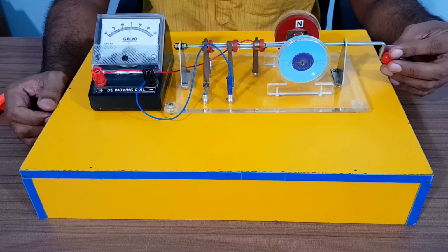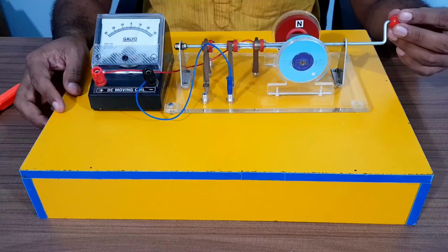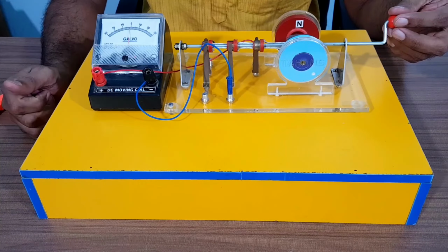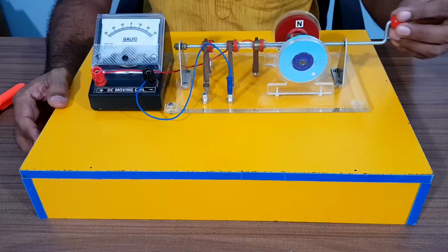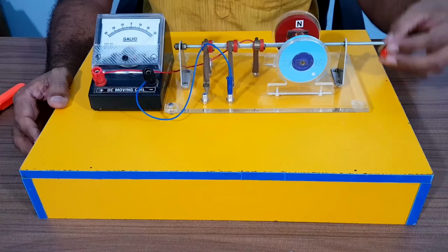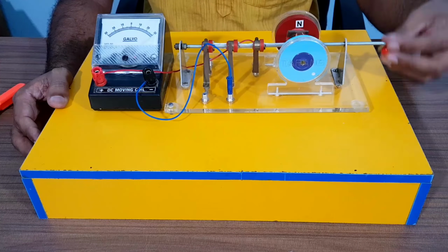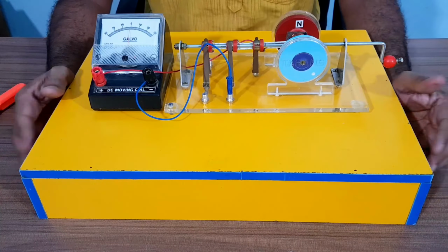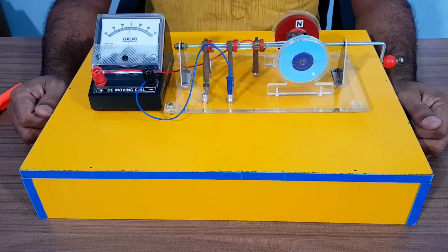But the first position, you remember, as soon as I move clockwise, where does it go first, on this side or on this side? So, left hand side. Now again I will move it anti-clockwise and we will check where it goes first. See, though the starting position is different, when you move continuously, here you are generating AC supply with current changing its direction 50 to 60 times a second in real generators. So this is how an AC generator works, and we are also going to make a simple model of an AC generator. But before this, we will understand what is Fleming's right hand rule.